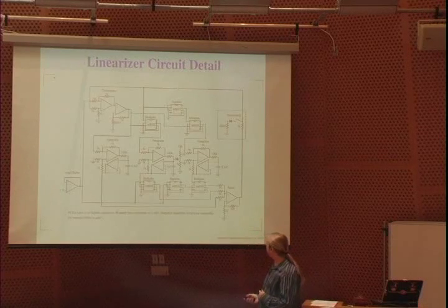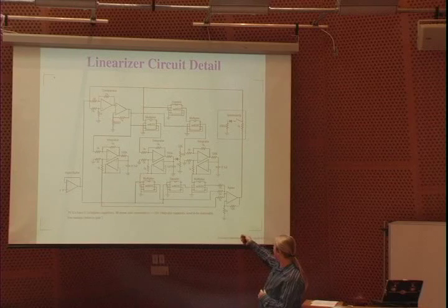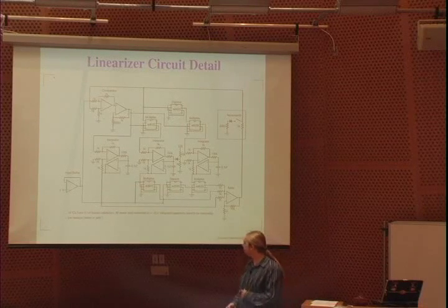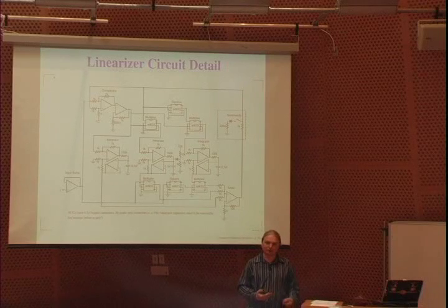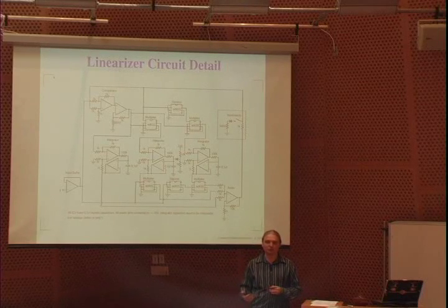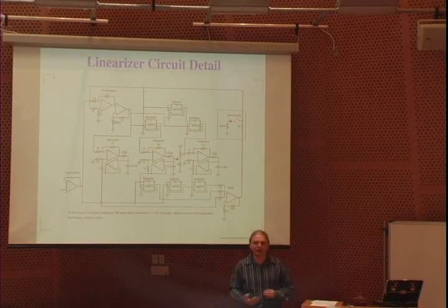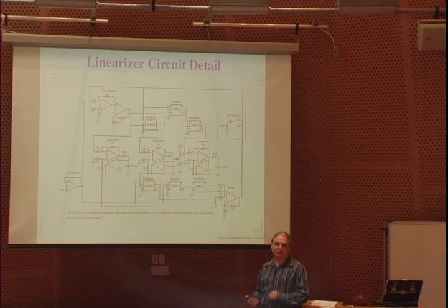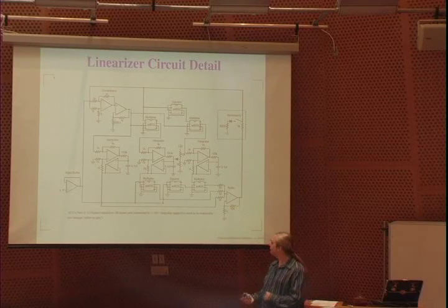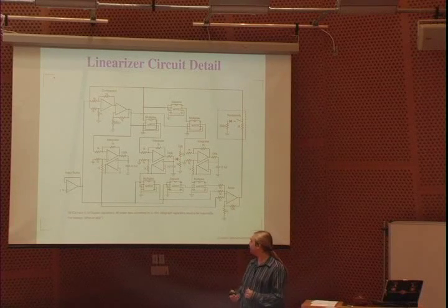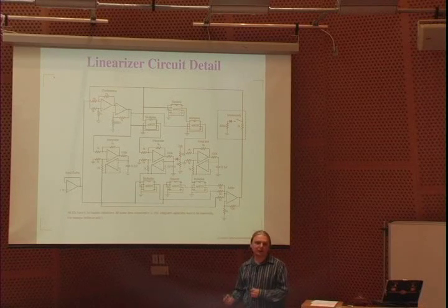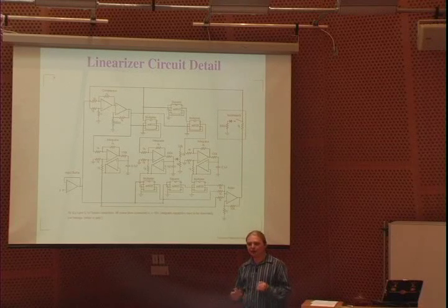If you build a circuit to do this, this is a circuit that I built to do this. It has just over a dozen major components, so multipliers and op-amps. It's building a second order Taylor approximation. There's a little diode there that restricts it to the space of monotonic models. That's an attached constraint block, as I mentioned.